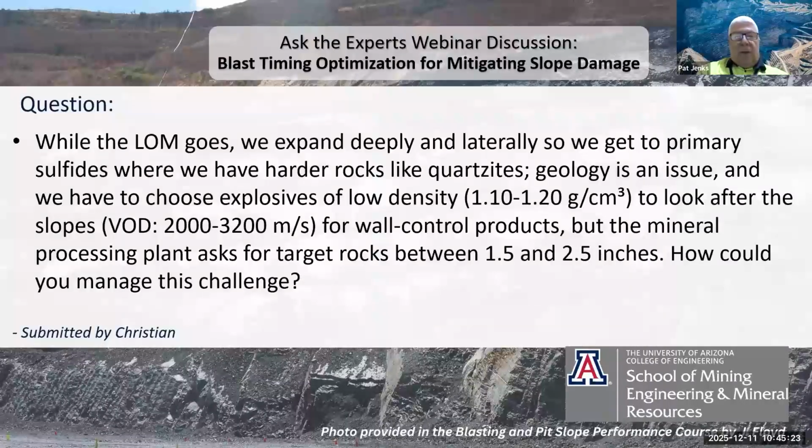There's got to be a give and take there, and that also influences the geotechnical slope design. For example, if we are damaging that rock mass near field to the high wall, we're going to likely have flatter inner ramp slope angles, and our waste stripping ratios are going to be higher than if we took a bit more care with that wall. So there's a lot of things to consider in here, and it needs to be a really broad conversation between a number of the stakeholders at that site.